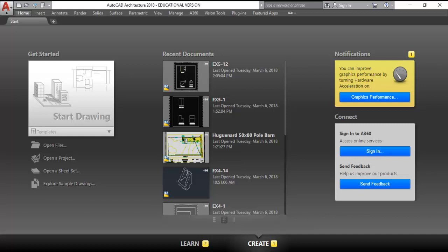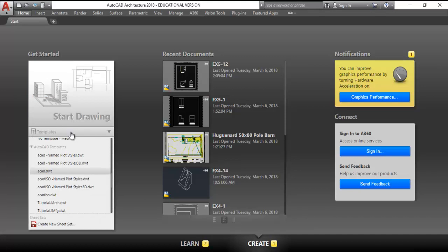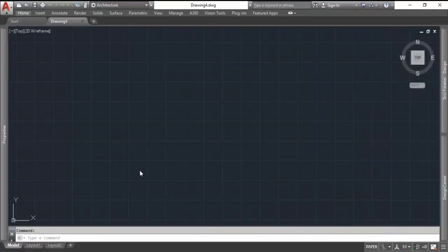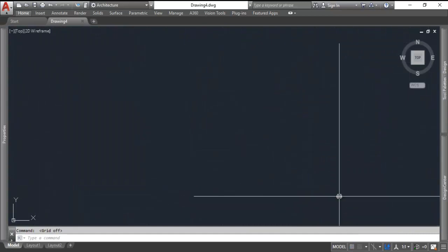So we're given the front view and the top view. We need to draw those two as well as the right view. And it also says prepare a three-dimensional sketch of the object, which should be done isometrically. So this is all in metric, so we're going to use template ACAD ISO. And once that comes up, turn off my grid and we're good to go.